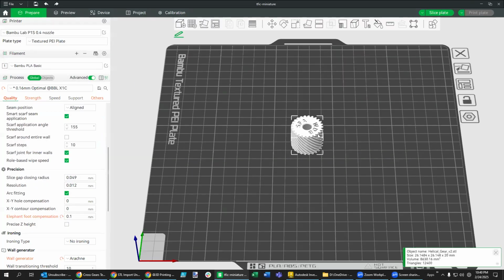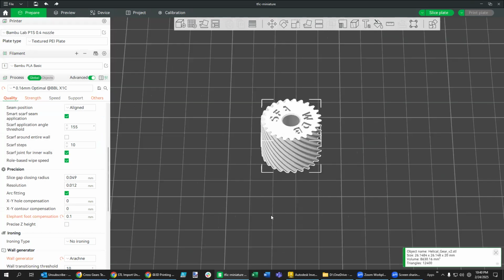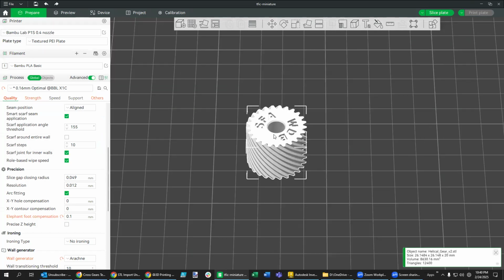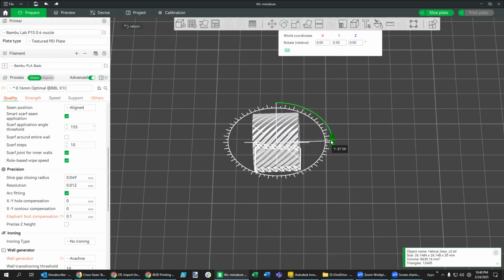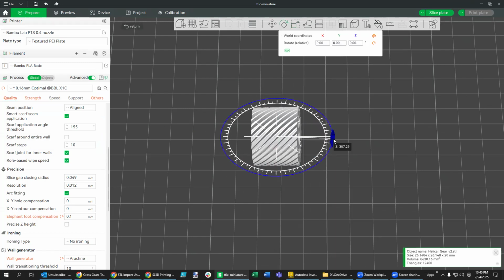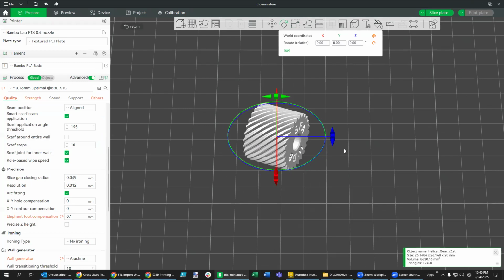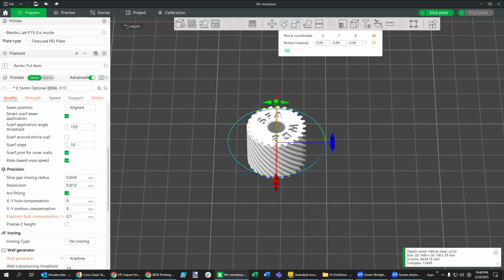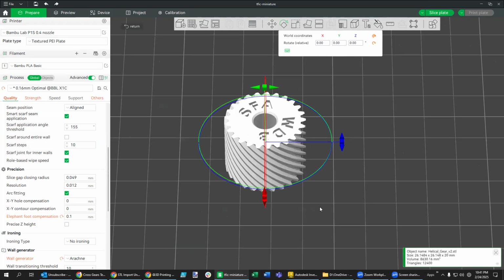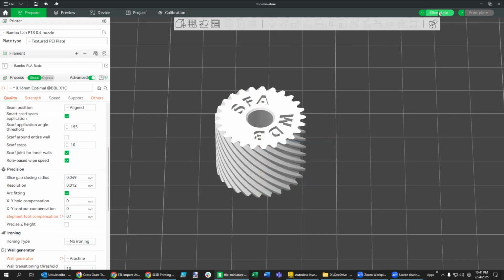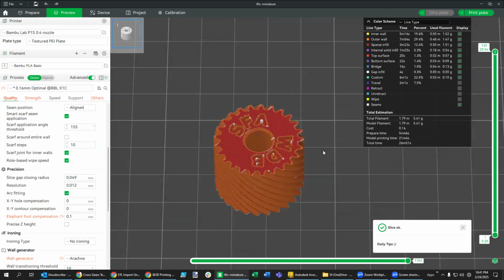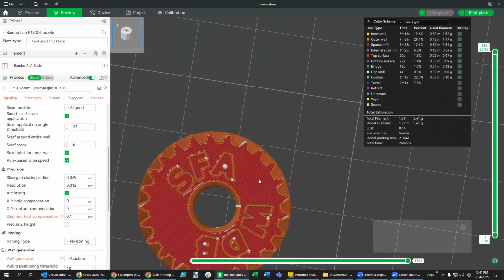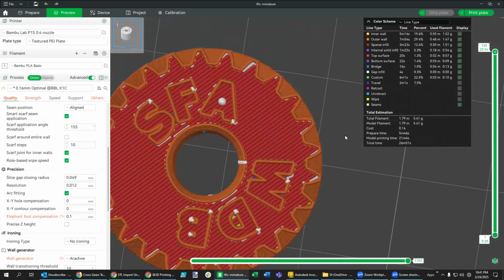Now, if it's not sitting up and down like that, you certainly want to rotate it over, but it looks like I got lucky. Sometimes you'll find that these are lying on the surface, or more likely, flat. But what you do is use some kind of automatic adjustment like this. There should be no supports, and you'll see that there's no brim or anything like that, because it's just drawing it straight up and down, or extruding it straight up and down.